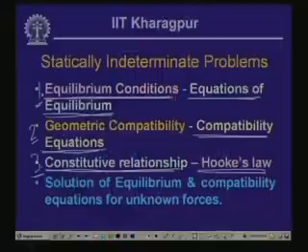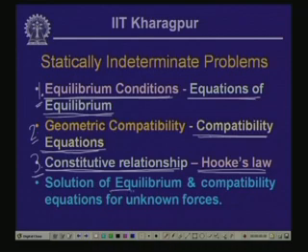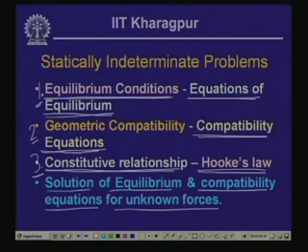So, we have one equation written in terms of equilibrium criteria, and another written in terms of compatibility criteria, from which we can solve for the unknown internal forces.